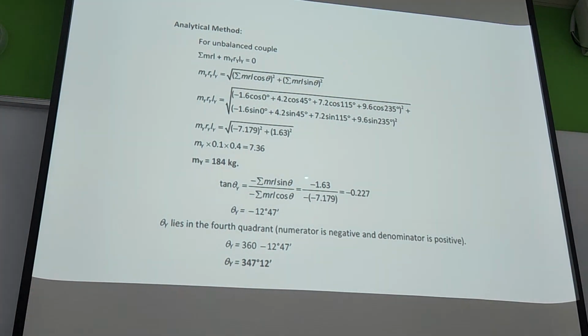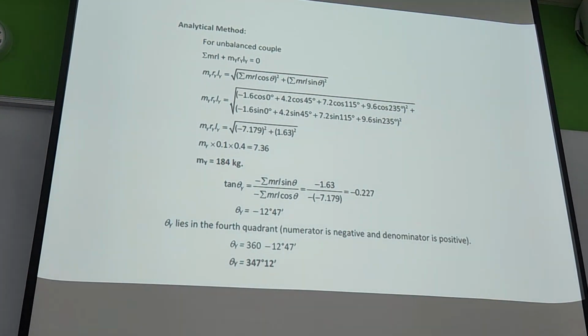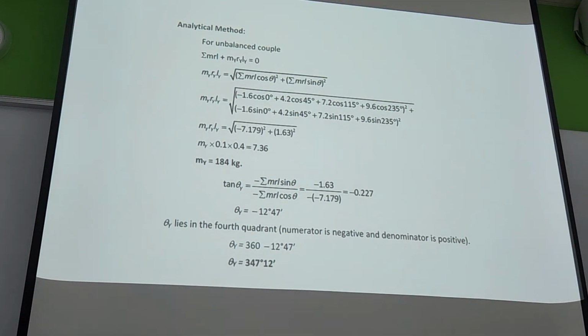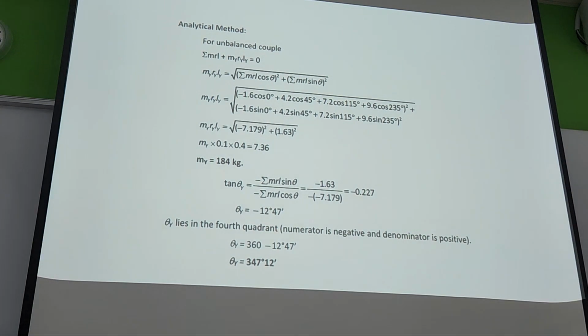But at what angle? Again, you take the Y component over the X component. Simply, tan theta is Y by X, so theta is tan inverse of Y over X. Here Y means the Y component of all the forces on the masses. There are 4 forces, so 4 X components, 4 Y components. So you can do this: the sum of moments acting on the system is 0. Then you know the mass acting on plane Y and also the orientation of plane Y.